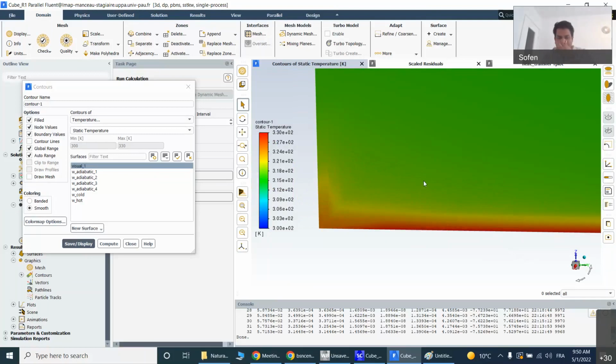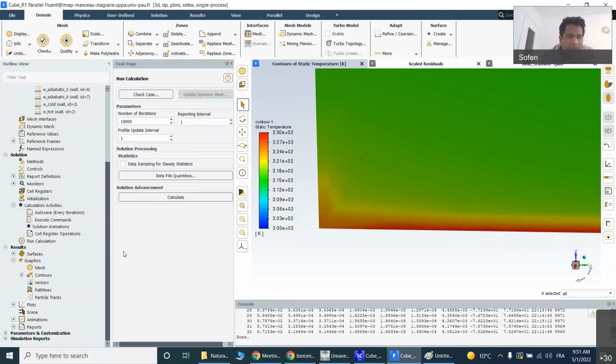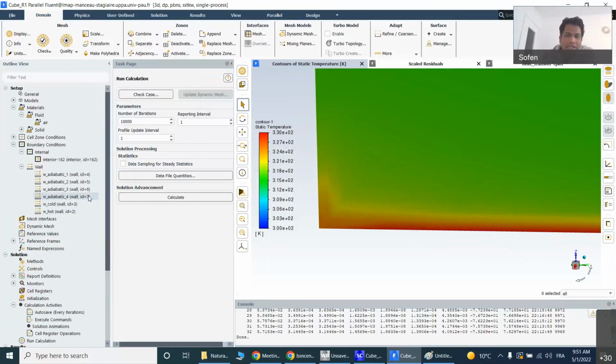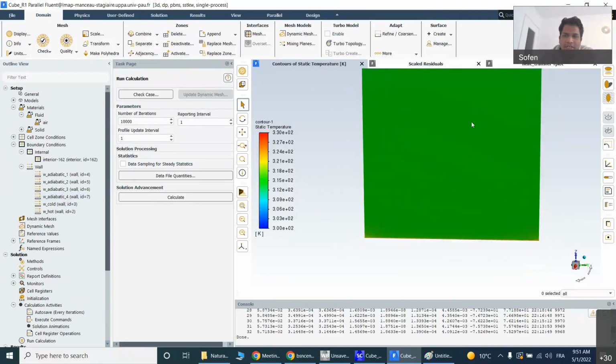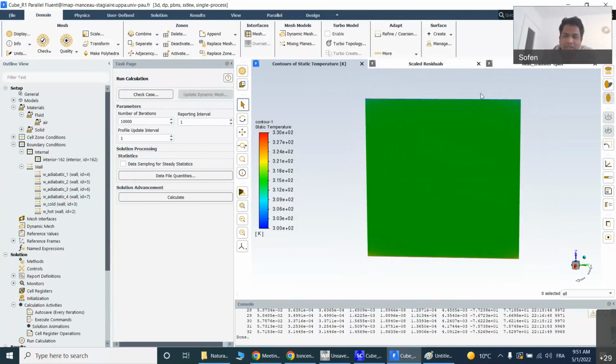Again, you're coming to a question. Okay, we can allow it. Coming to the question, how to model it as a forced convection, mixed convection. I cannot call it a forced convection now because we have a buoyancy effect here. We have a forced convection component here. So it is a mixed convection, right? Both buoyancy and the external mechanism that drives it.